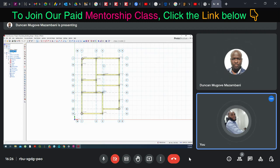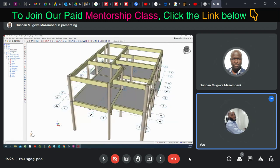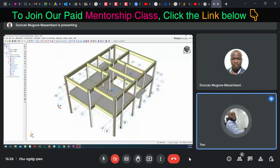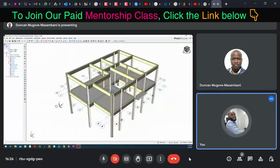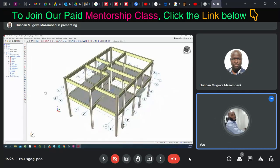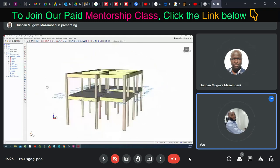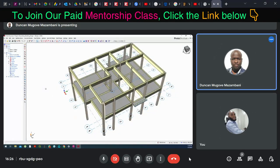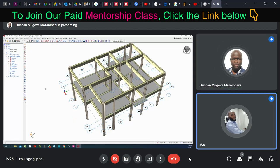3D view, yeah, that place. Okay, that's fine. Now, since we don't have slab at this roof level, we are meant to reduce the depth of the beam from 450 to 300. So we'll just subtract the depth of the slab, which is 150, and we are left with 300, right? So right now, just stay on this view.